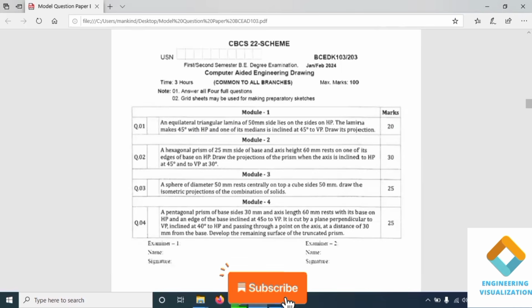Okay, so here is problem number 4: a pentagonal prism of base side 30 mm and axis length 60 mm rests with its base on HP, and an edge of the base is inclined at 45 degree to VP. So that means we need to place the pentagon at an angle of 45 degree to VP. It is cut by a plane perpendicular to VP, inclined at 40 degree to HP, passing through a point on the axis at a distance of 30 mm from the base.